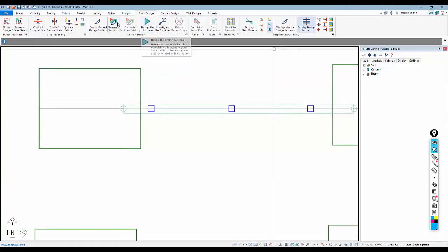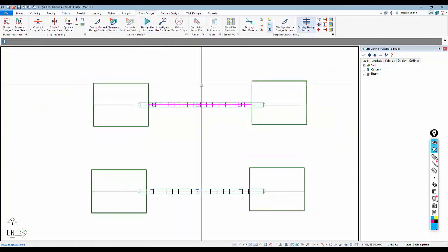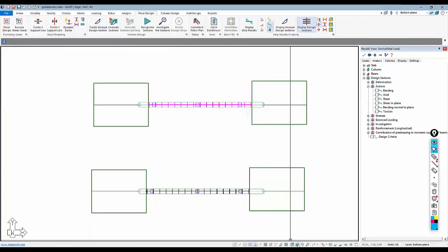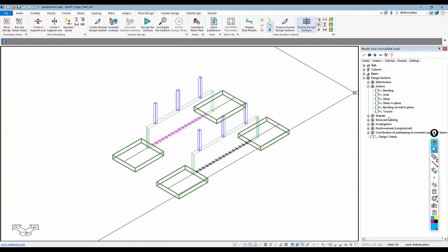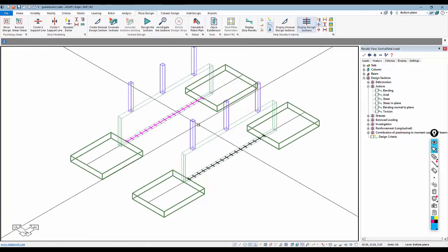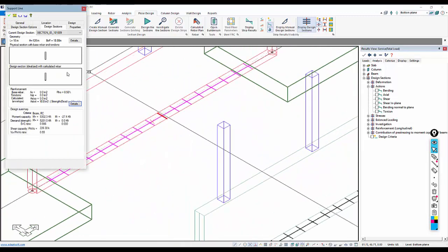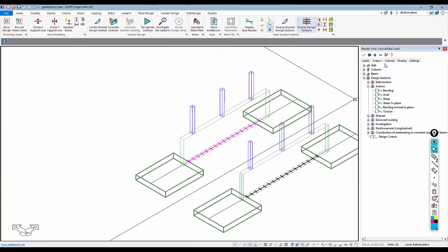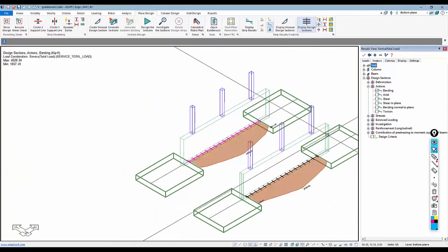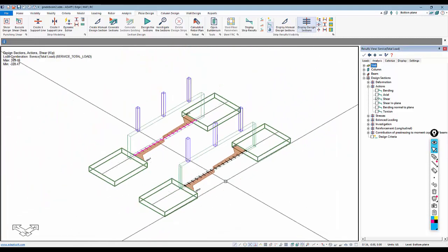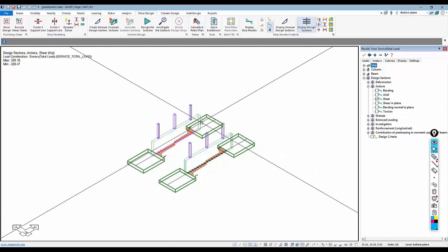So I'll go ahead and generate the sections. You see we have 2 support lines. I'll design those cuts. And again, if we wanted to review results for those cuts, they're shown here at the reference plane, but they apply to this beam. If we double click on any of the cuts, we can see the physical section. The depth here is 120. And now we can generate, for example, actions for those cuts. So looking at the bending action, shear, and so on. This then allows us to directly design the grade beam.